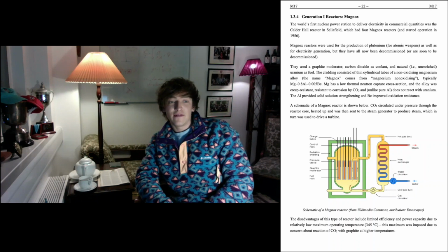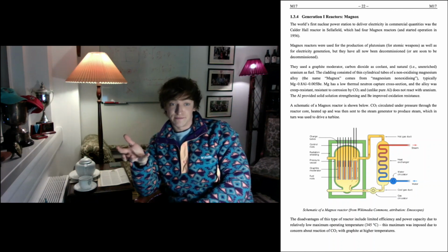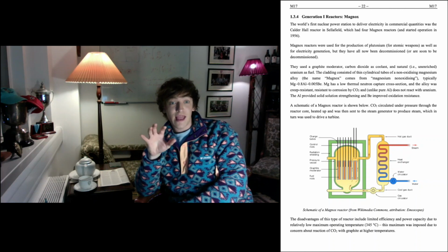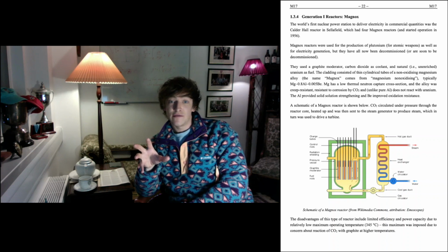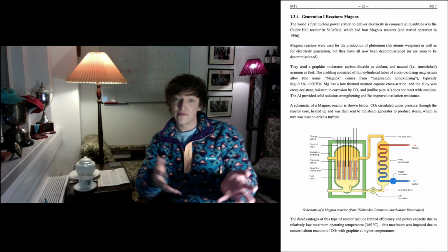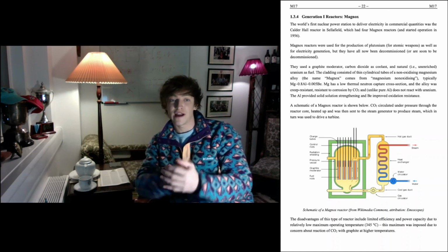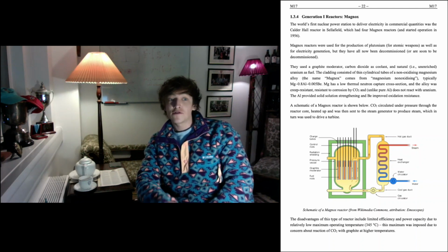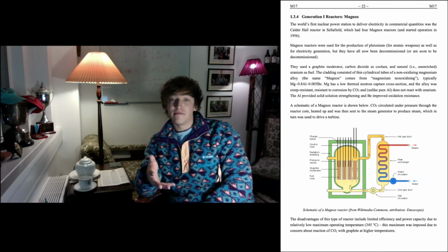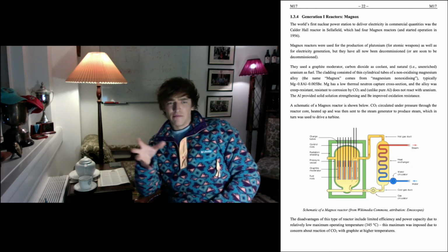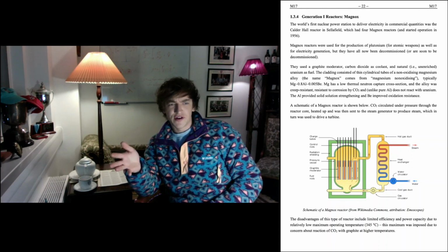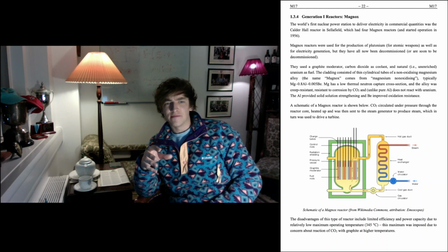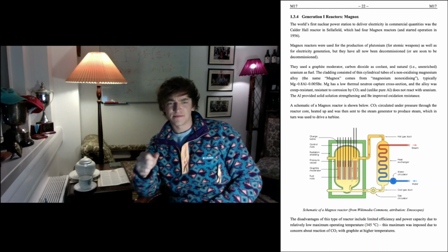And the alloy proved to actually be quite creep resistant. So it was a very positive alloy to use. And it was quite resistant to the CO2 coolant used in those reactors, which are known as gas reactors. CO2 in gas form, gas-cooled reactors. And also it was quite unreactive with respect to the uranium. It was actually cladding, it was holding. And they added the aluminium and beryllium to improve strength. So you get some solid solution strengthening, and the beryllium helps oxidation resistance.